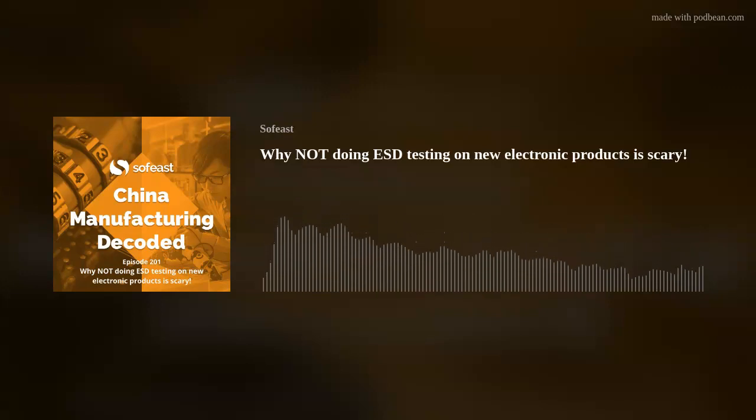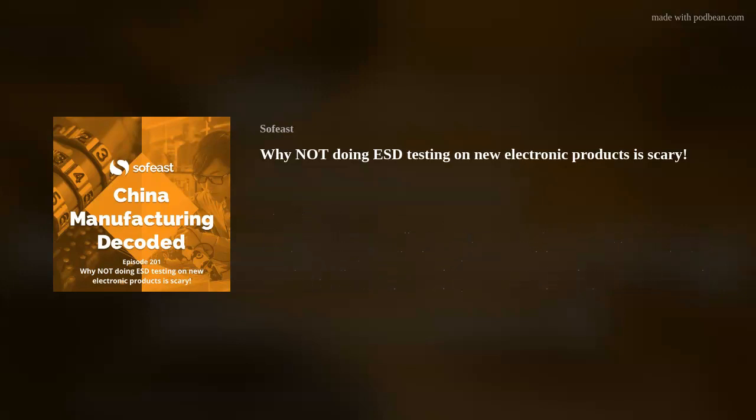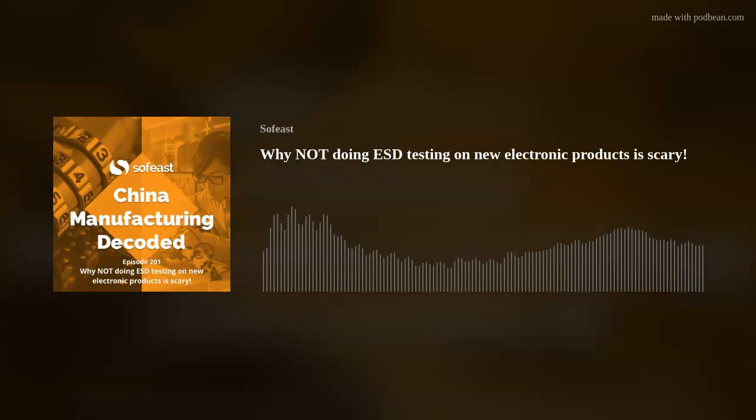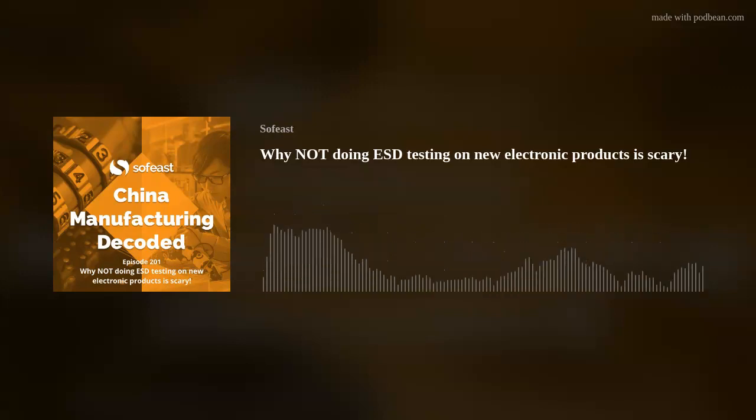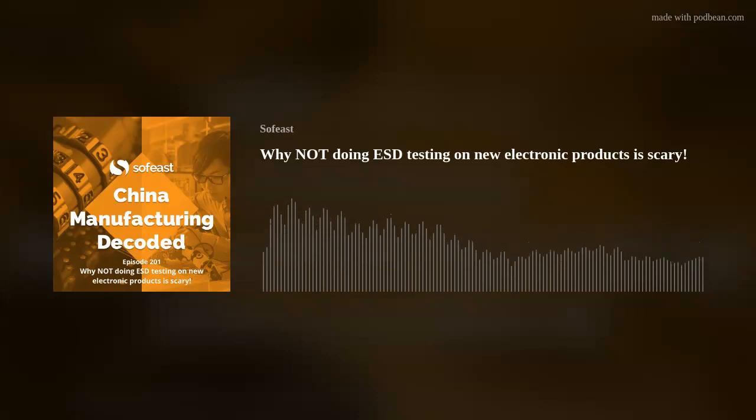Then you could also send one of those devices to run full ESD based on your ESD requirements. And if the compliance hasn't been done yet, you could do it at that stage, right at the start of production when everything goes well. Then you do one more compliance test. If you can do these harmonically, then most likely you'll avoid a lot of customer issues, field return issues, and financial disparity. Yeah, that's absolutely what we want to avoid.